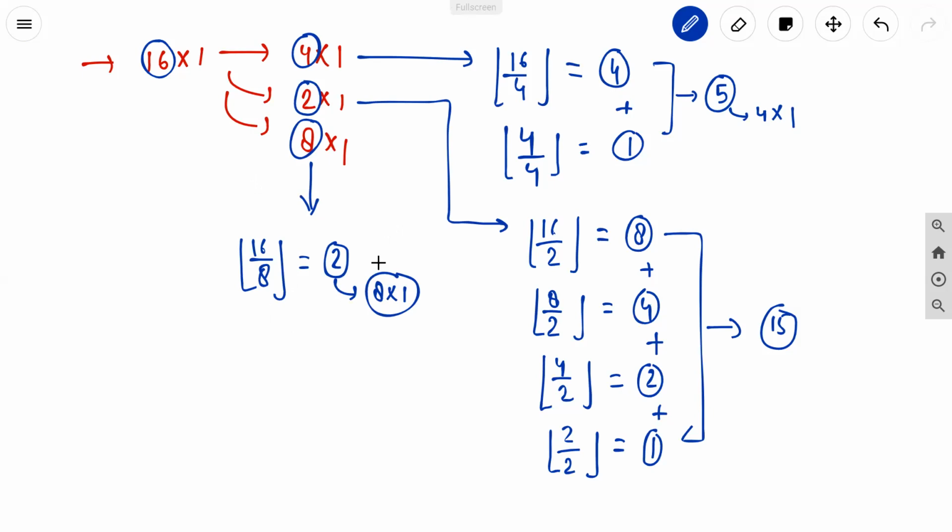And for these two outputs, we can only use a 2:1 mux, because the value we remained with is only divisible by 2. So overall, we will use 3 mux, where 2 are 8:1 mux and 1 is 2:1 mux.